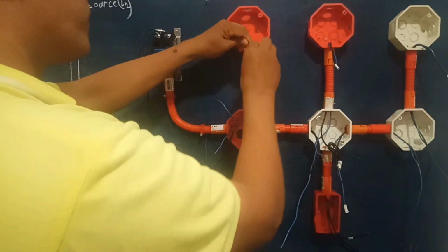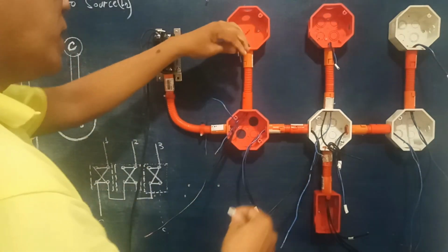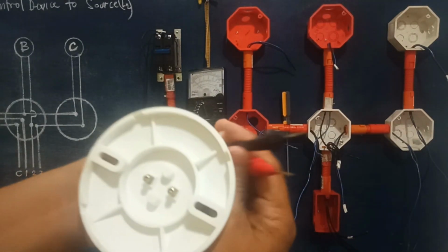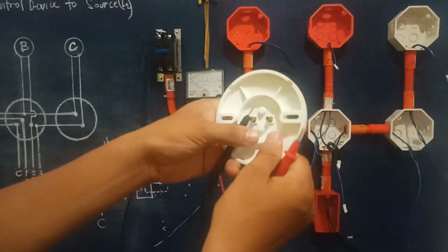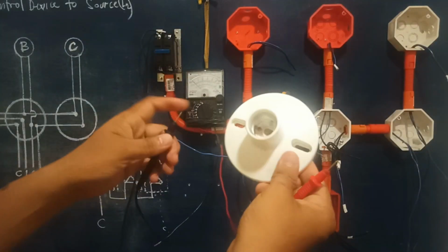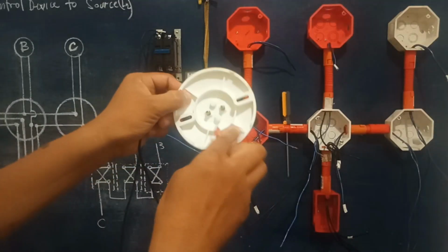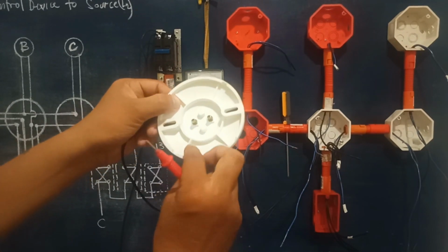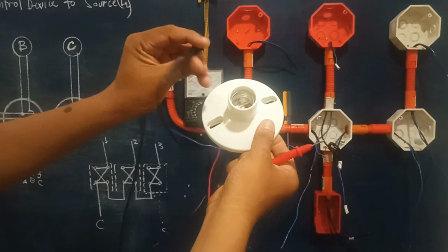So we're gonna remove first this electrical tape right here. Then, in this case, we're gonna check it first as to which of the 2 terminals here is intended for our neutral line connections. So that is a very important one.